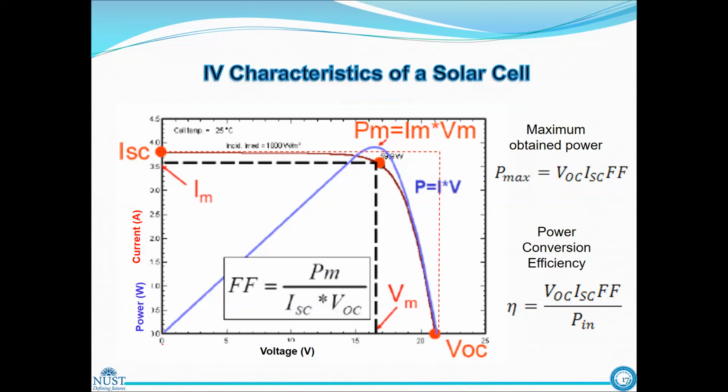When there is no voltage, we see a maximum value of current passing through the circuit. This current is known as the maximum current, or simply, as there is no voltage, the short circuit current. This short circuit current is actually the light-generated current because there is no applied voltage at this stage.